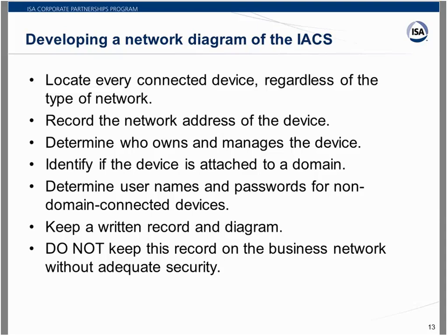Identify if it's attached to a domain. A lot of these devices, particularly controllers and PCs, might be authenticated through a Windows domain for centralized password management. However, a lot of times they're not. Maybe they can be added fairly easily to make it easier to manage your passwords. But you need to identify the device that is attached to a domain. And which domain is it and who manages that domain? Go through and audit the names and passwords for the users on every device.